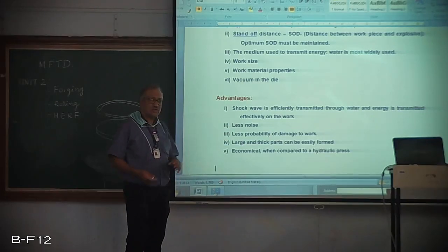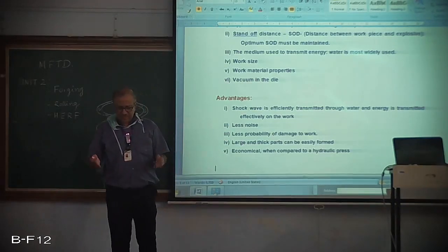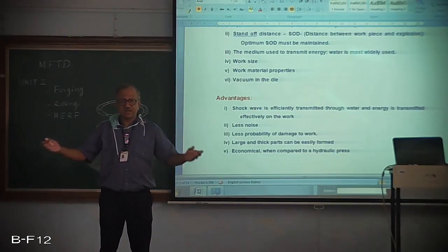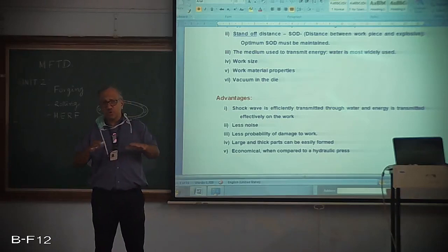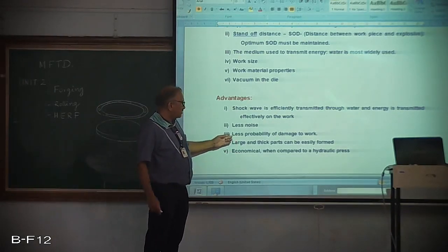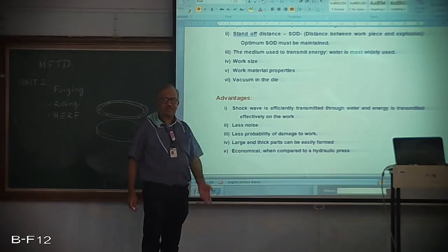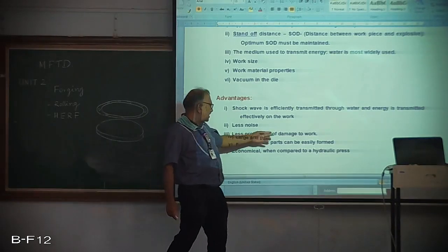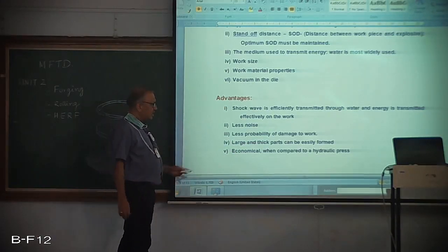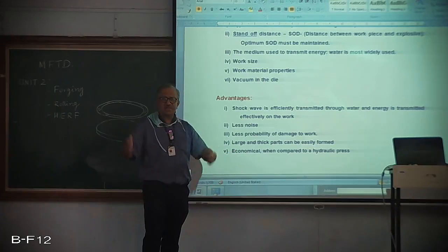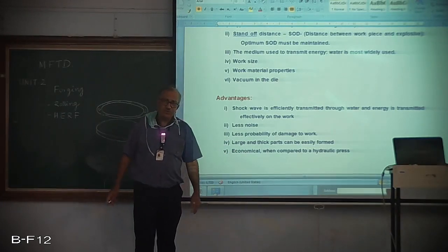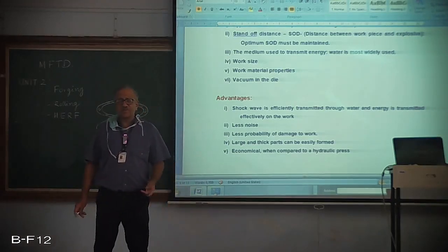And of course there is less noise because of the fact that it is underwater explosion, and also because the entire arrangement, the tank itself, is below the ground, so less noise is there. And of course because of the cushioning effect of the water, there is less probability of damage to work, and very large and thick plates can be easily deformed in one step without much of a problem, which would mean a lot compared to conventional deformation.